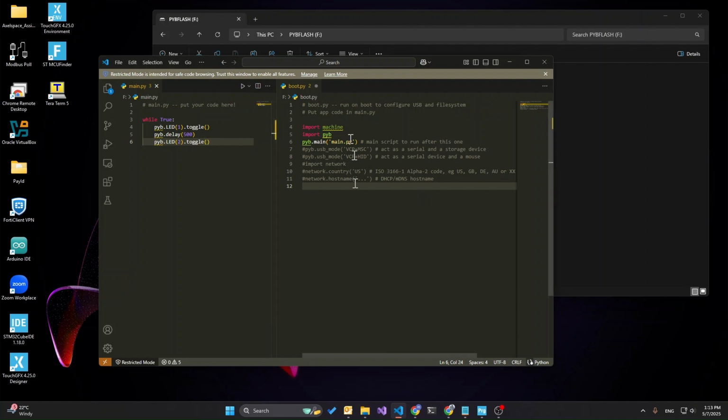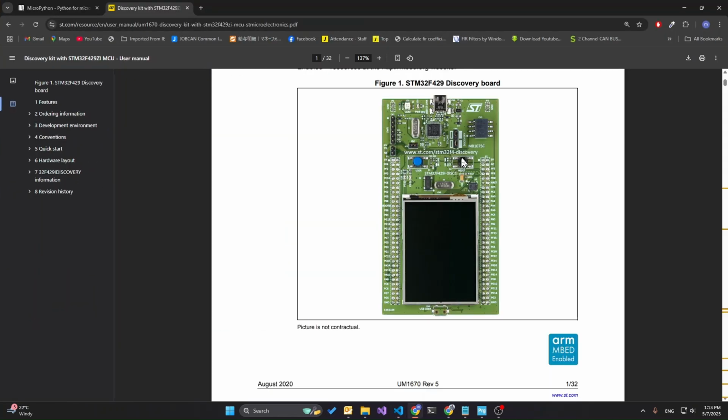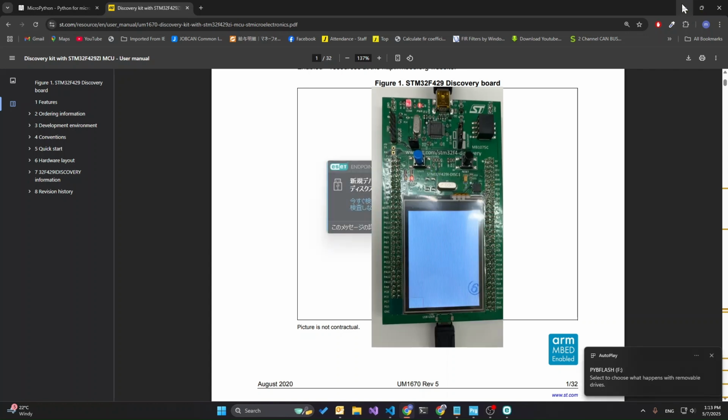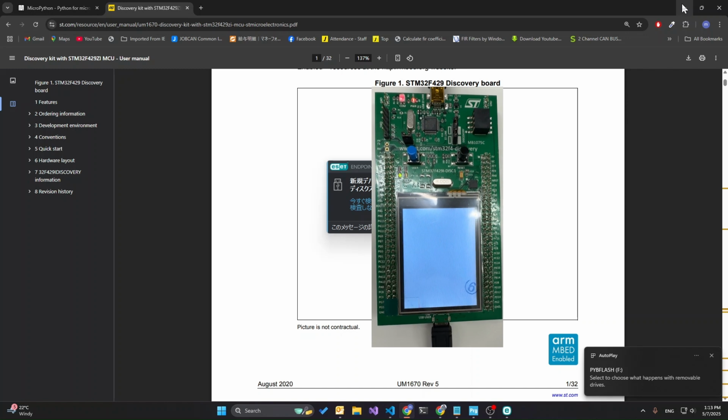Save both files. Before reset, wait around 6 seconds to ensure the file is saved properly. You should see LED 1 turn on briefly and then turn off. Once it turns off, press the reset button. The blinking LEDs should now run continuously.